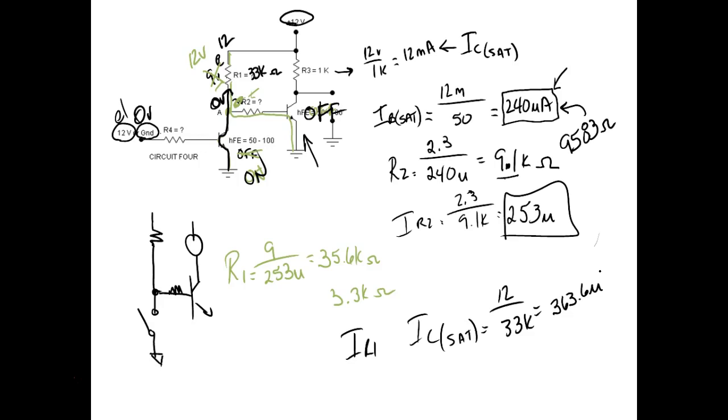And of course, when we add the other transistor, we get gain out of that, right? You understand? So here I go from 363 microamps, which is not what it's going to be because we hadn't sized the resistor. Are we okay? Okay, so what size of the resistor? This guy's going to drop 11.3 volts.